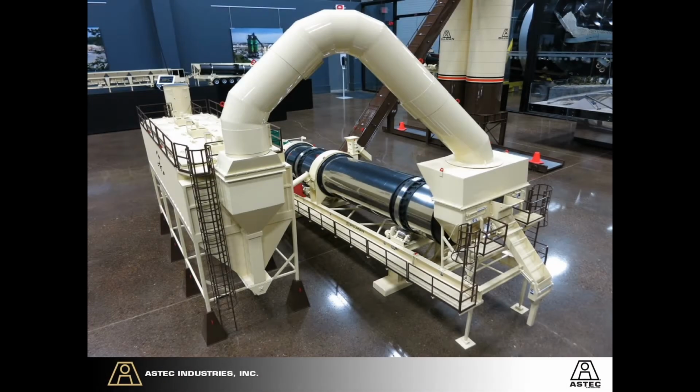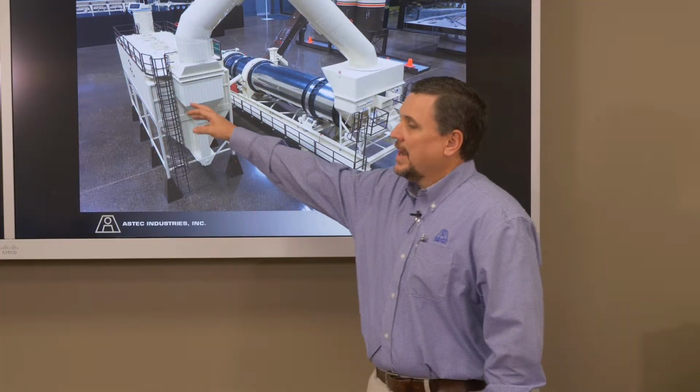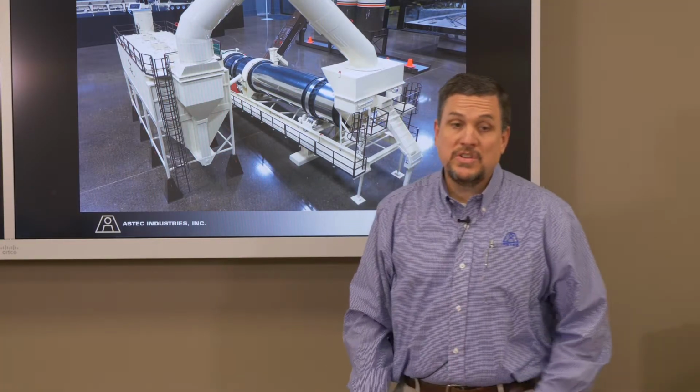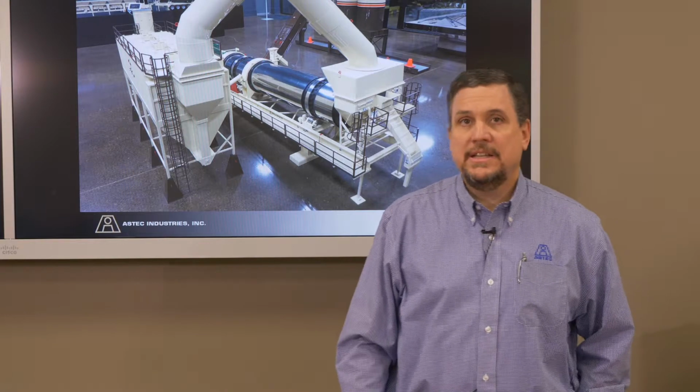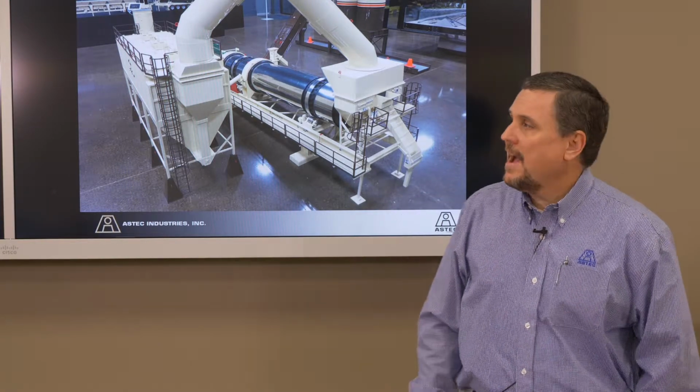This is a different style baghouse. This is pulse jets, what we just looked at, but this is a reverse air, or a roto air, is what most people call them, roto air baghouse. This roto air is a little different in that it has sets of turrets. And these turrets, it's more of a mechanical style baghouse. It uses outside air instead of compressed air to shock the bags with.